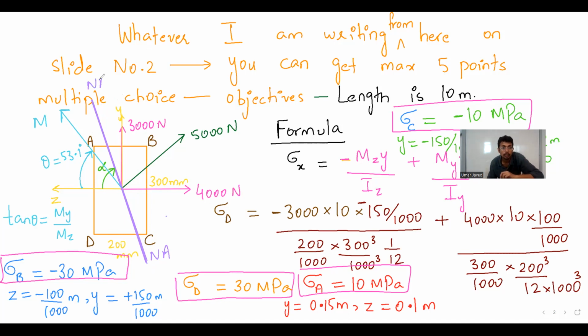Now tell me, where would the maximum bending stress lie? Where would be the maximum bending stress for this problem? We have to go away from the neutral axis. Good. And you know how they figured it out? They said we have to go farthest away. So they started going farthest away. Right? And which are the points that are farthest away?